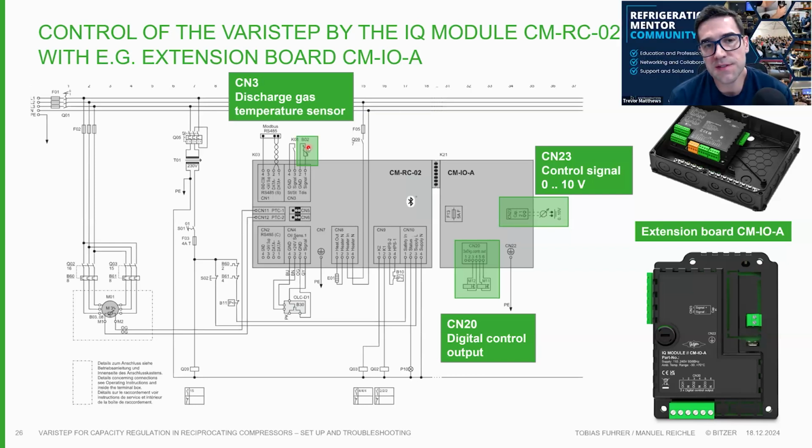So is that a specific sensor? Is it a 10K and 86K? Is it a specific one for that? Say one fails in the field, they check the resistance. What would the replacement be for that sensor, and does that come with it? Because I tell every technician, you've got to be putting discharge protection on your compressors, because if you overheat, the compressor is going to die, and it costs a lot more money than a $20 or $30 sensor. You know what I mean?